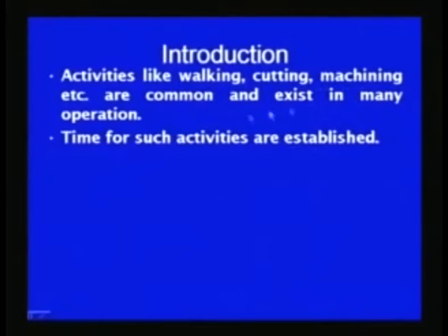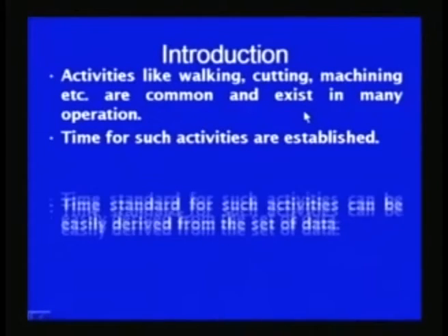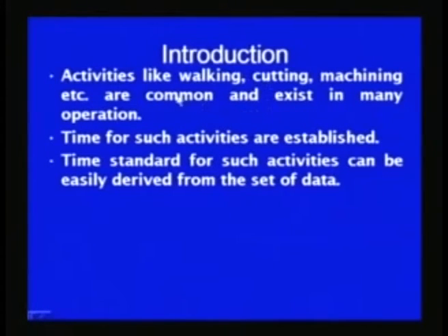The standard data method is another method which is commonly used for establishing the time required to carry out the job. There are various activities which are very frequently carried out in industry, like walking, cutting, machining, and if the time values are available for these simple activities, then the time values required for other operations in which these activities are carried out can be obtained from the already established time values.